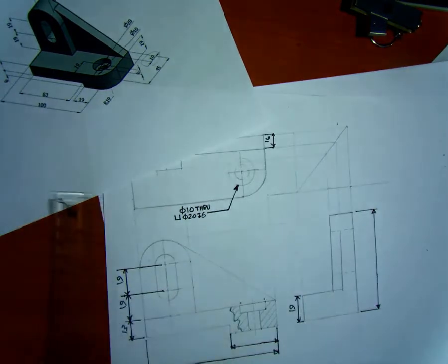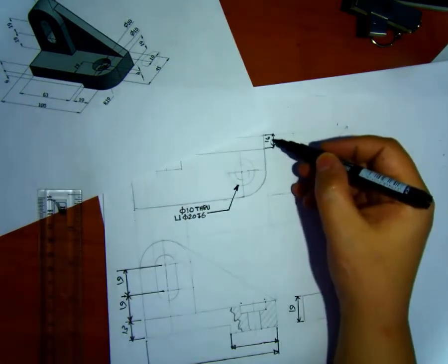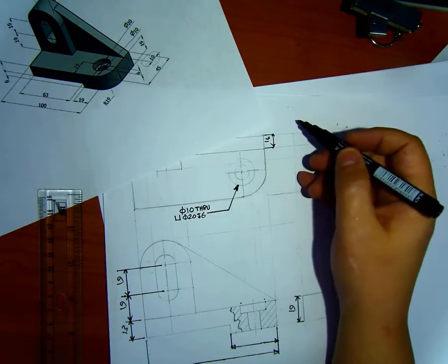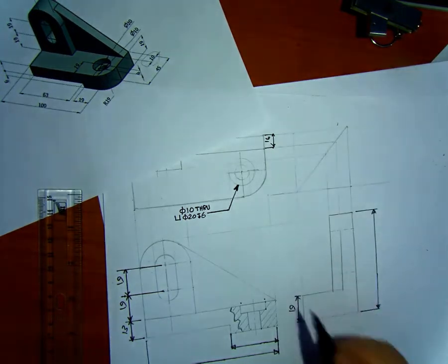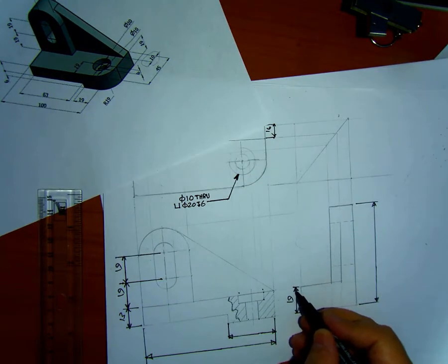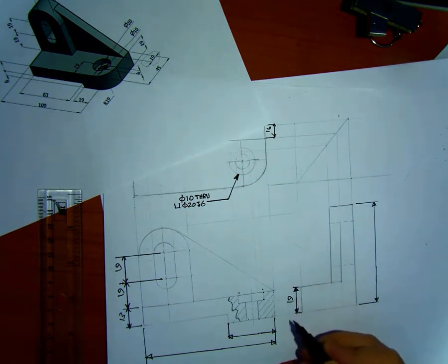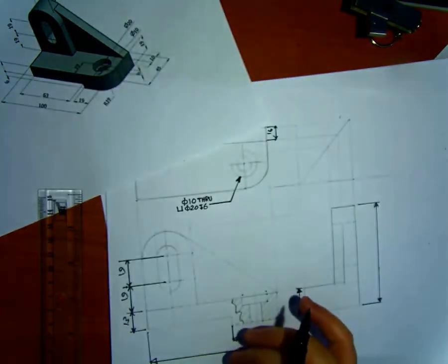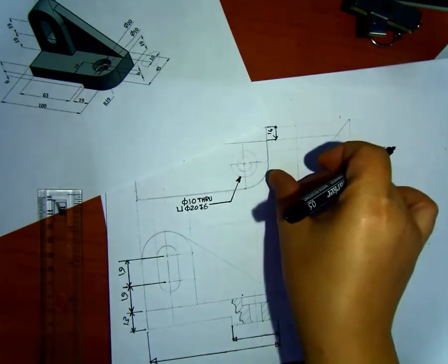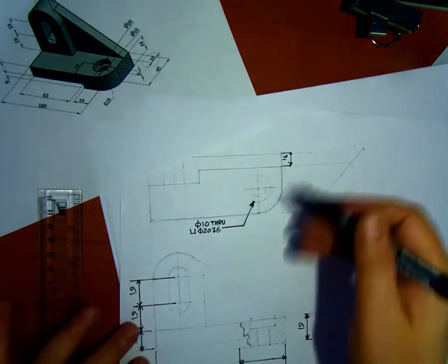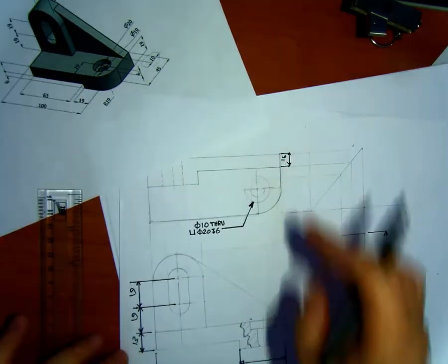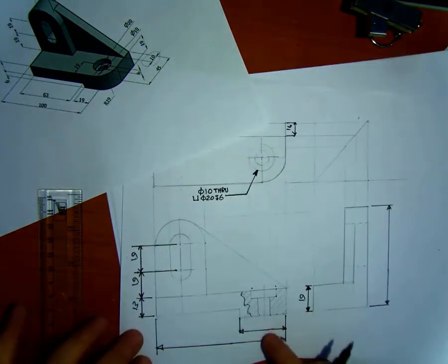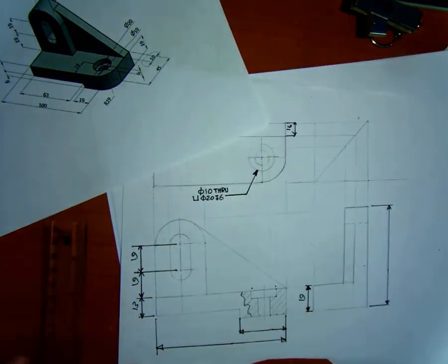There are, by the way, two alignments for numbers. There is this one, called aligned, and then unidirectional. I will show you in detail in the lecture. If you start with one of them, you cannot use both of them in the same drawing. As an example, now I am aligning the dimension like this, vertical. So you cannot draw the dimension normal to the view of projection, to the view with these verticals, unless you are drawing the dimension for horizontal, which in this case you can.